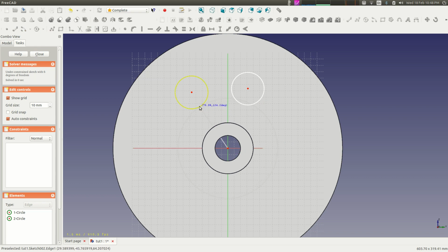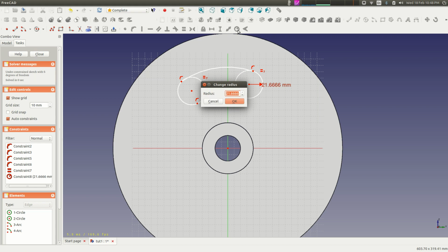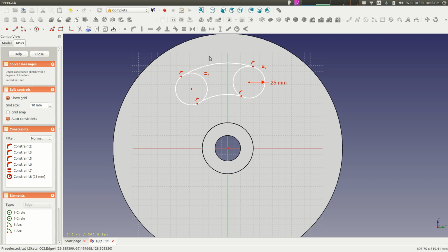I'm going to make the sketch just as before. I want those connected, and I want these connected. So it's kind of working there. I can kind of drag it to make it work. I'm going to make this smaller. So now here's a great case for the snip tool. First I'm just going to make these the same. So another constraint is to make things equal or the same size. So I've made these two circles equal. So if I define the diameter of this one maybe as 25, it'll immediately change the other one. So that's really nice.